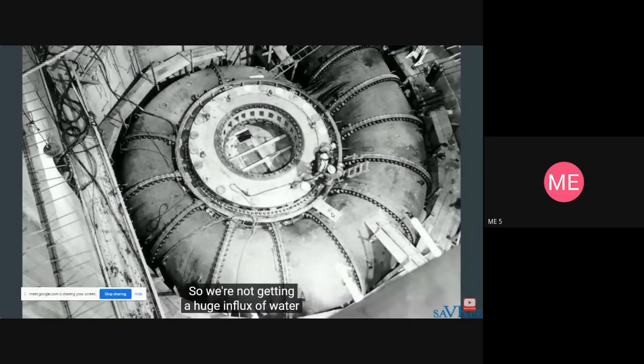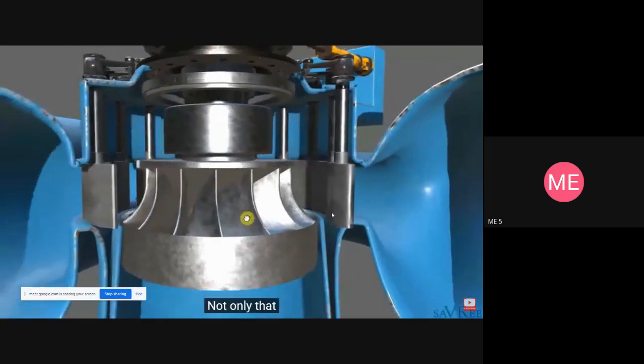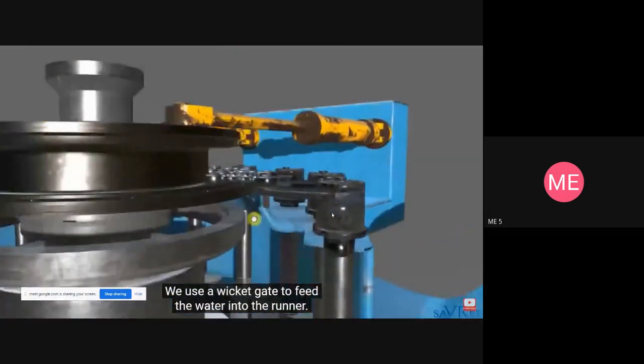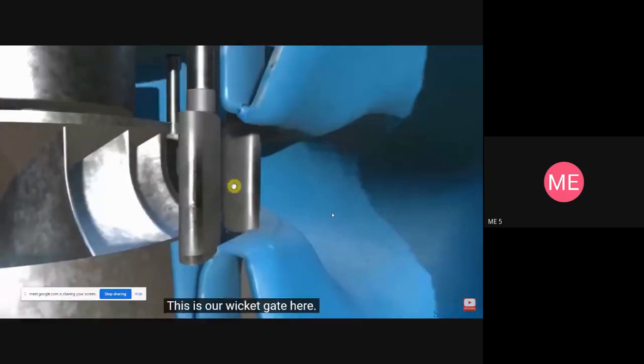A huge influx of water that just flows into the runner on one side would cause an imbalance, potentially vibration, which may even damage the runner. Not only that, but the runner is going to operate inefficiently. We use a wicket gate to feed the water into the runner. This is our wicket gate here.